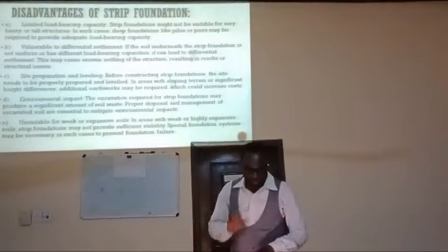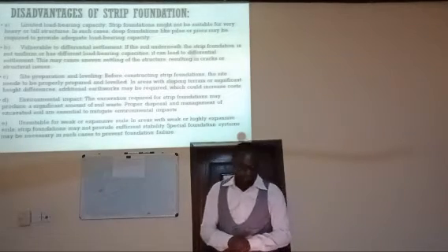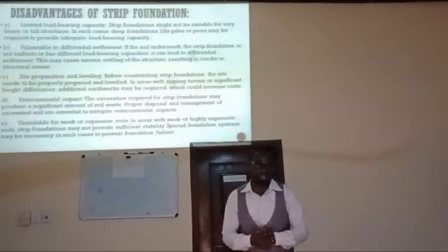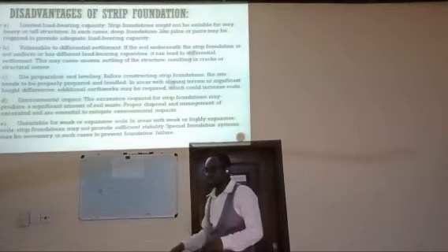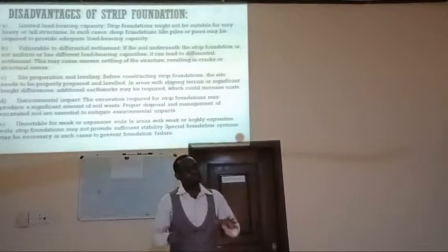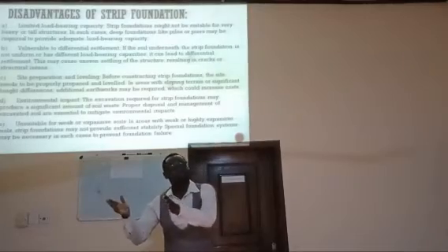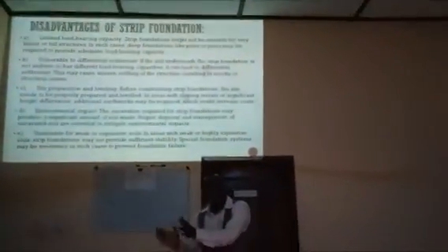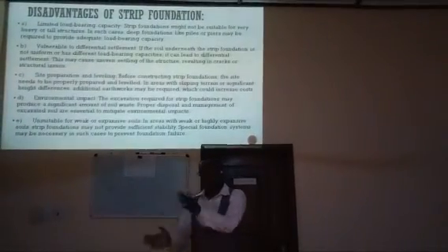Number three, it is difficult to prepare site preparation and leveling for strip foundations. It's more difficult because you need to come to site, look at it, use a surveying instrument or whatever, check the levels, and know where to place what you want to do, so it may take longer.